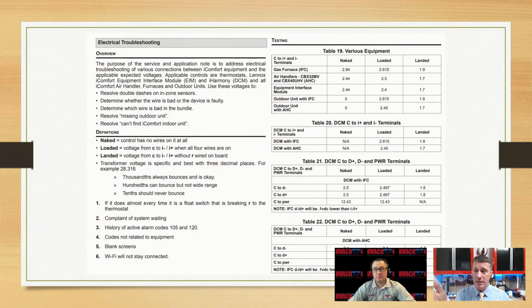It is very sensitive. So if I have oxidation, cuts, nicks, breaks, or splices, oopsies. If you're on a communicating system and there's an existing splice in your control wire, the very first thing you do is run new wire. If you can't run new wire, the second thing you should do is grab your snips and cut it off.